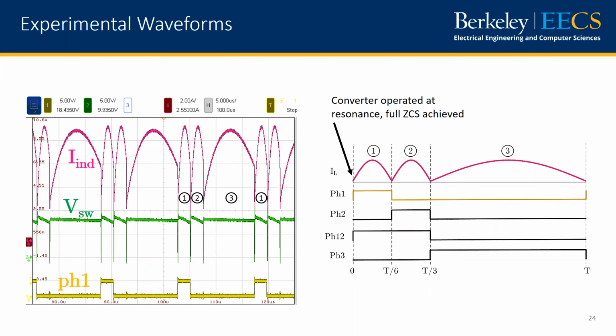Yeah, it's more a question of will your resonant frequency itself change? Oh, yes. The actual resonant frequency would change, because it's dependent on that effective capacitance. So it could change based on tolerances, and it might slightly affect what the waveforms look like, but we haven't noticed any major problems with the tolerance.